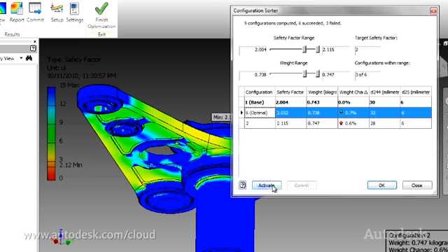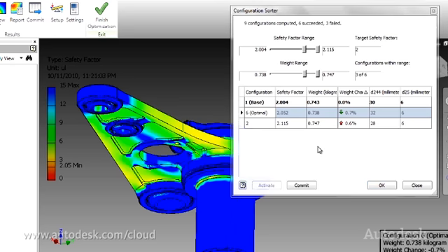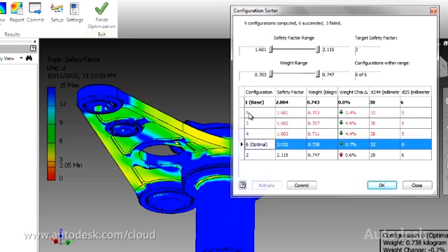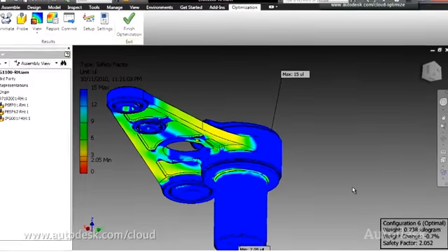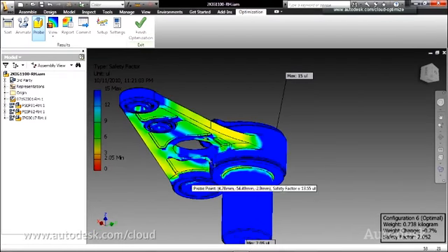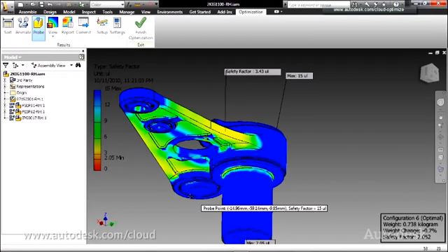By manually adjusting both the factor of safety and weight ranges, we can view all of the defined assembly iterations. One of the biggest advantages of the Inventor optimization service is that it automatically sorts through these versions and displays only those that meet the defined design criteria.